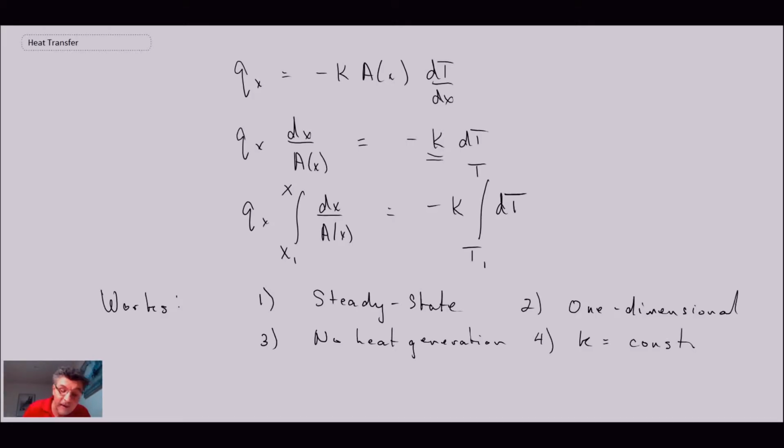And what do we get out of this? Well, you get T of x and you get q of x. So we were able to get the heat transfer and the temperature profile. In terms of engineering, this is usually the one that we are most interested in, because we want to figure out what the heat loss is. So what I'm going to do now is summarize the 3 different systems that we looked at. We looked at the plane wall.